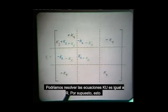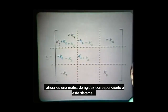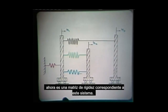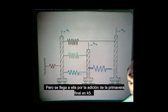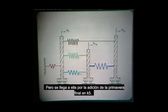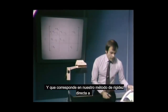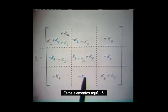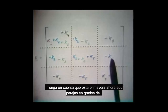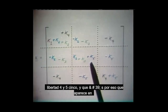We could solve the equations Ku equals R. Of course, this now is a stiffness matrix corresponding to this system. We have not quite yet reached the system that we want to analyze, but we reach it by adding the final spring, K5. K5 now is here, and that corresponds in our direct stiffness method to adding this spring in there, these elements here, K5. Notice that this spring now here couples into degrees of freedom 4 and 5, and that's why it appears in column 4 and 5 here.